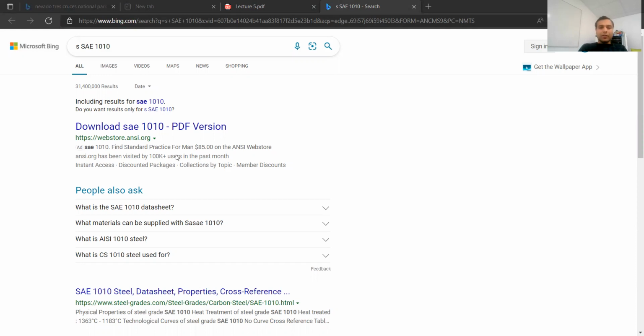Now, when we have a look at the steel composition or the standard composition, let's say it's SAE 1010. The first 10 represents that it's to do with the steel. The other digits represent the percentage of the carbon, 0.1%, 0.2%, 0.3%, and so on. So this is how the composition of the steel is designated. Every material is designated a number, and we work based on that number.